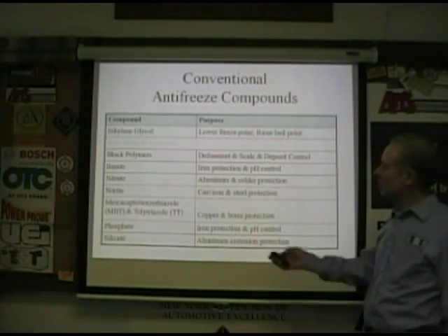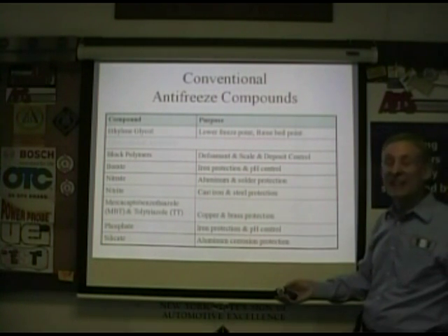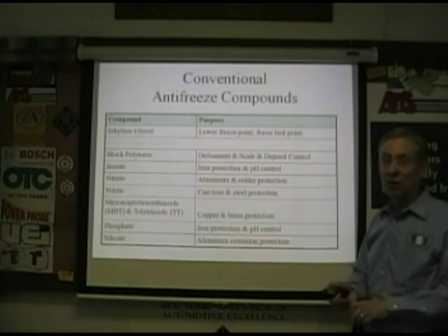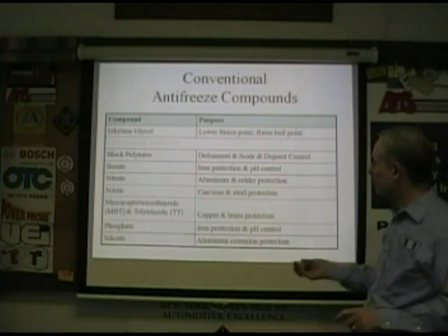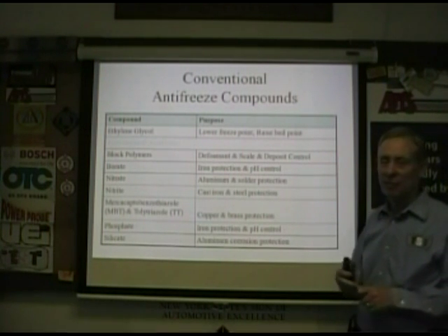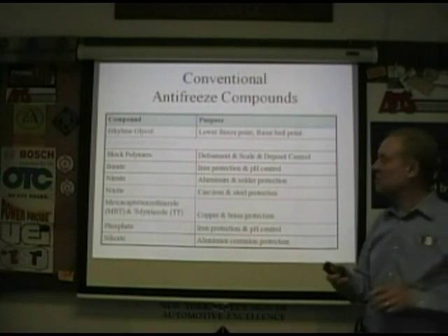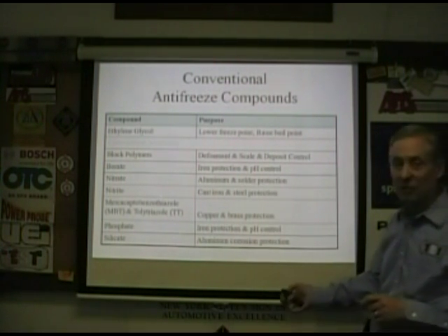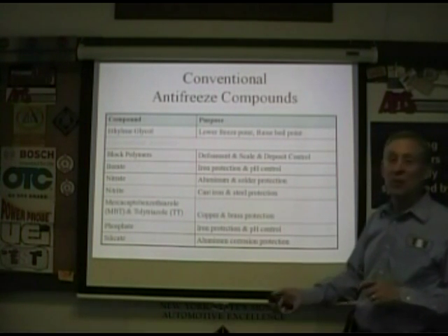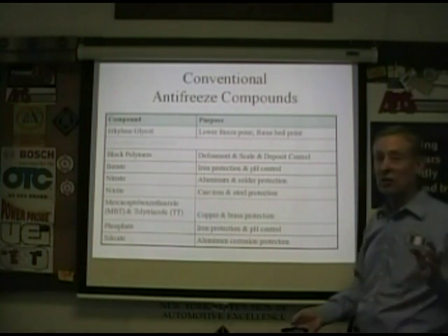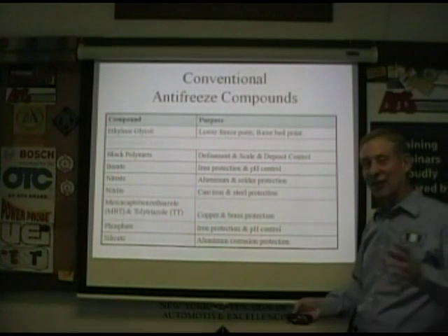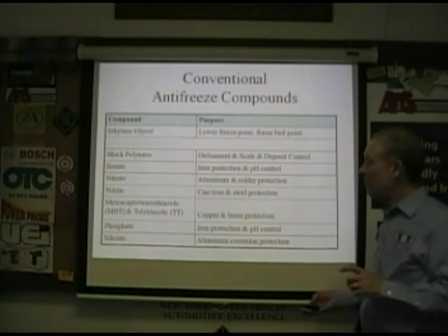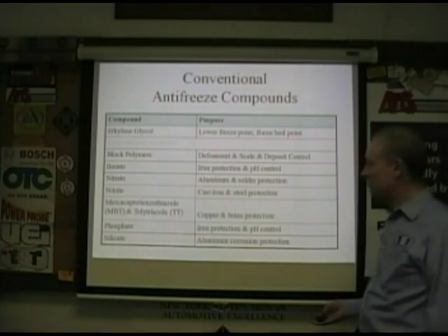The bottom line is there are additives that are used for different purposes in coolant, lowering the boiling point, reducing corrosion. We don't really talk too much about water pump lubricants nowadays because we have modern materials, but there are substances in there for that, and there are compatibilities between all these chemistries, so that they'll react with each other if you mix them and cause all kinds of unintended side effects. It's like the drug commercials on TV. You don't want all those side effects. Talk to your doctor first.